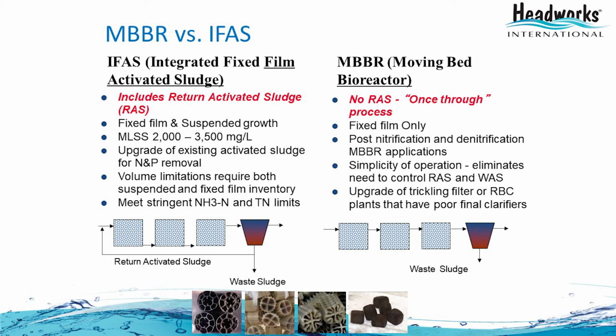These are suitable for retrofitting existing activated sludge systems or to shrink the footprint and reduce the cost. Clarifiers are cheaper compared to DAF, for example, but clarifiers occupy more space. But in IFAS, the reactors take less space. So in terms of overall footprint, MBBR or IFAS are somewhat close to each other, but if you have an existing activated sludge system, it's much easier to retrofit by adding media and including aeration requirements.